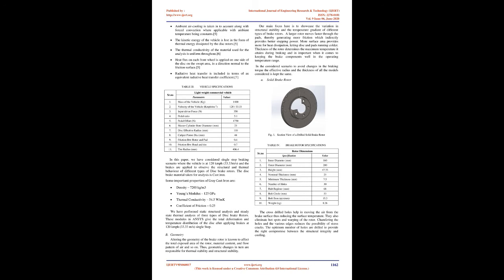2. The energy dissipated in the form of heat can generate temperature ranging from 300 degrees Celsius to 800 degrees Celsius. 2,3. Braking performance of a vehicle can be significantly affected by the temperature rise in the brake components. 4. High temperatures during braking may cause brake fade, premature wear, brake fluid vaporization, bearing failure, thermal cracks and thermally excited vibration. 4. Therefore, it is important to predict the temperature rise of a given brake system and assess its thermal performance in the early design stage.